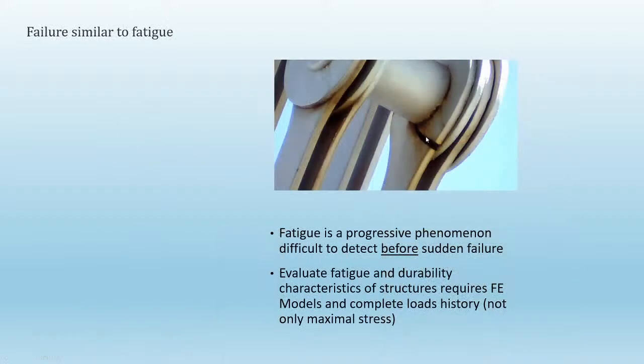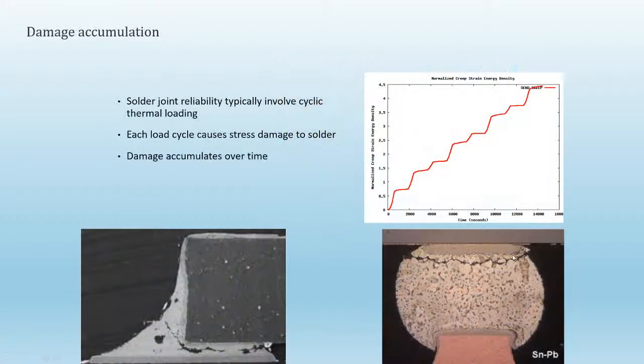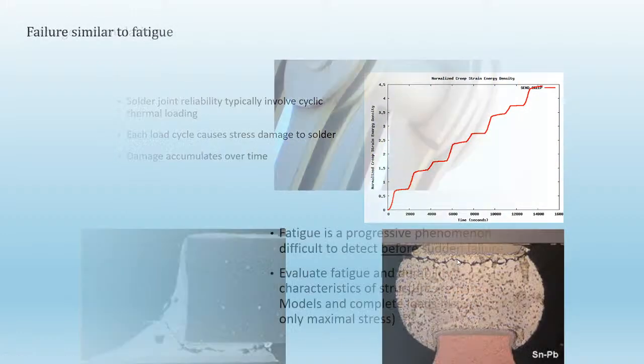If you look at solder cracks like this, it's on a very small scale. It's very similar to large scale cracks that we often worry about in mechanical analysis. Techniques like fatigue analysis have been around for a long time. Ever since the advent of the railroad and rail car, people have been worrying about cracks that grow through and cut through the axle and cause rail cars to derail. So this has been studied extensively, and mechanical fatigue looks pretty similar to what happens to a solder ball in that a crack grows across.